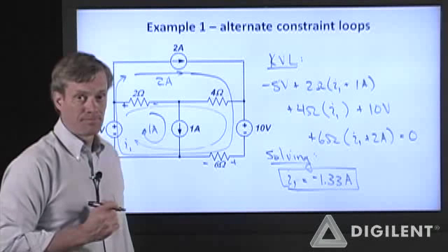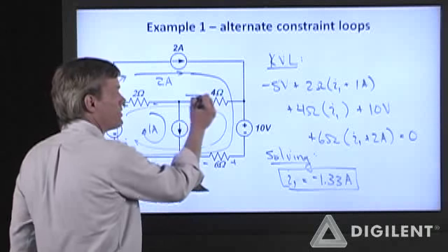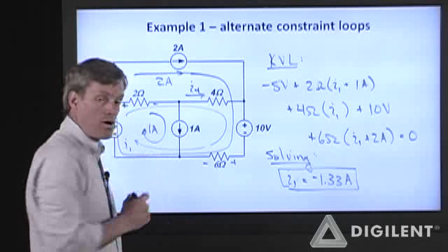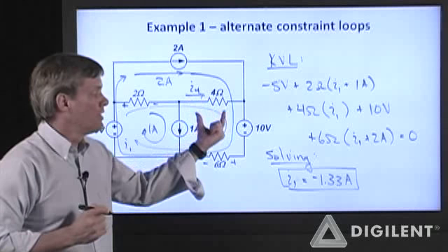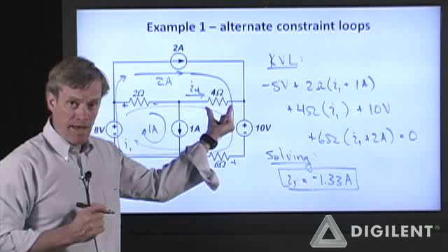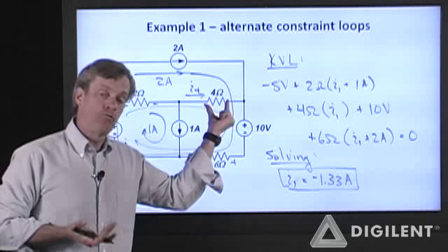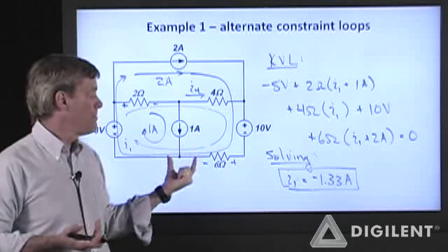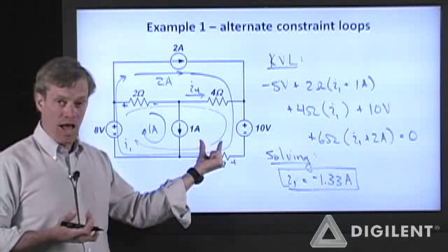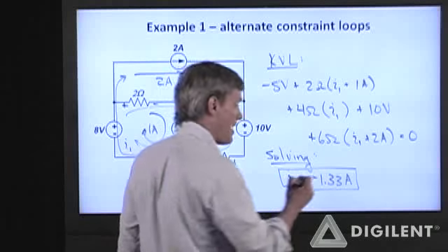Okay. This is still a mesh current. In order to find the current that I want, I4, I need to use my mesh currents, sum up all the currents passing through that resistor to get this one. However, now in the 4 ohm resistor, the only mesh current passing through that is just I1. As I said before, none of the constrained currents go through that.